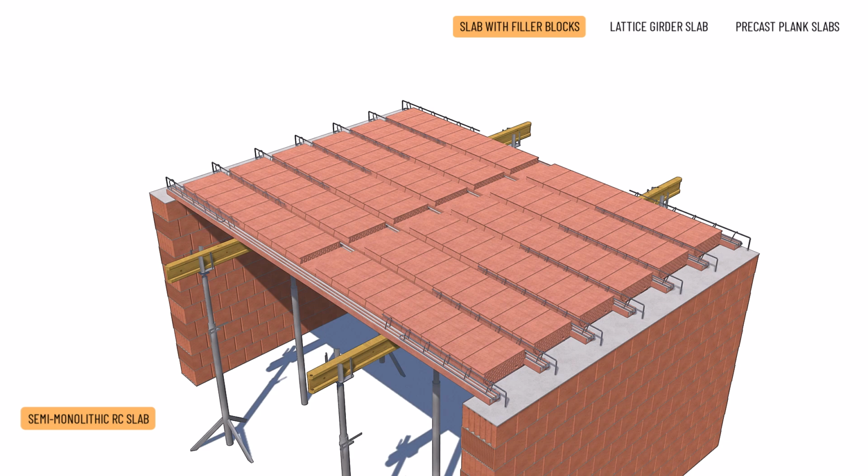The length of the top bar, diameter 10, is 1/6 of the span in the slab field, minimum 80 centimeters. It extends completely through the ring beam and is folded over the outer longitudinal bar.